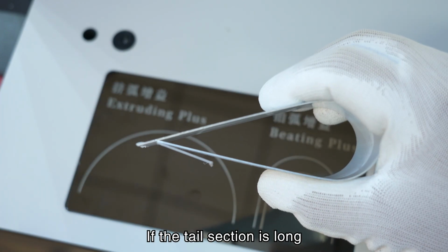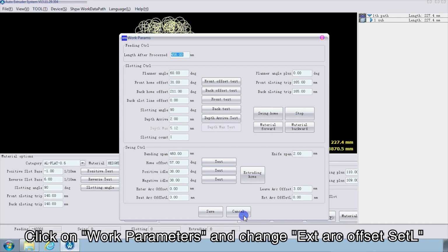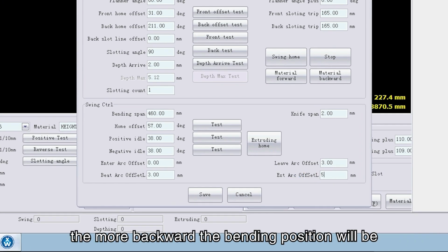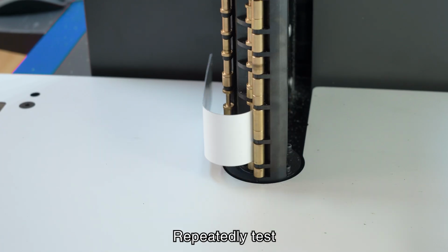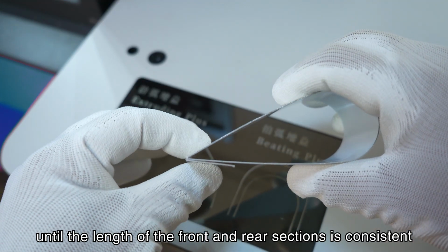If the tail section is long, it indicates that the bending position is closer to the front. Click on Work Parameters and change XT Arc Offset Settle. The larger the value, the more backward the bending position will be. Click to save. Repeatedly test until the length of the front and rear sections is consistent.